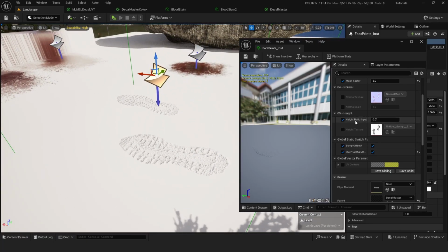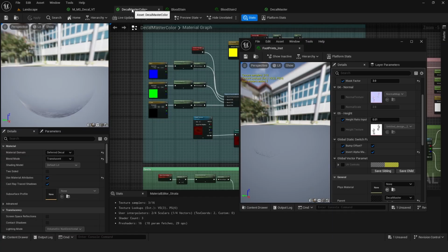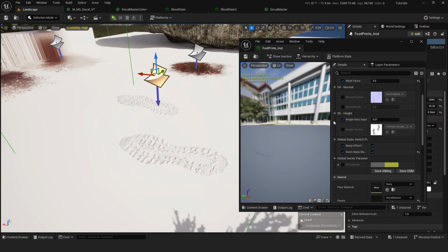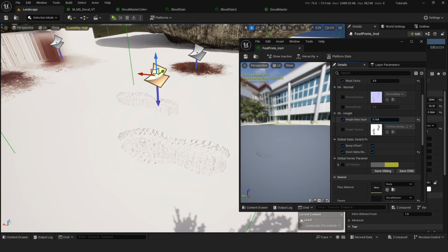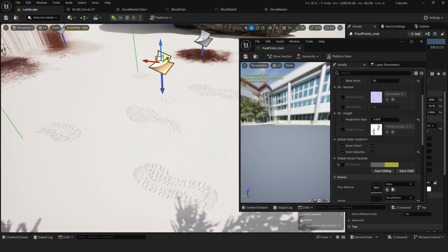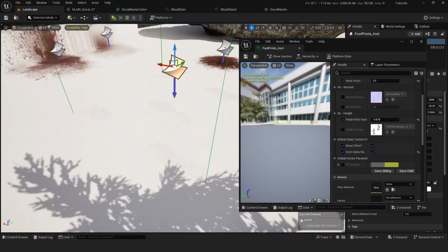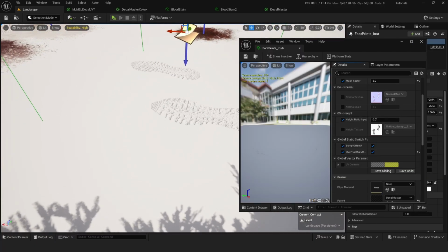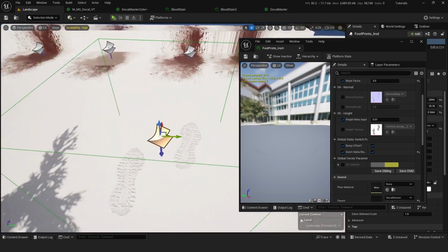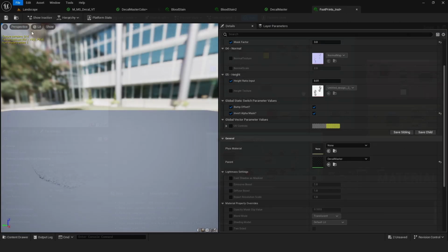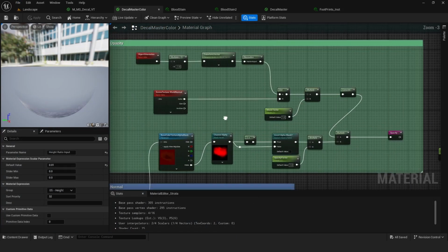And if we change the height ratio input, which was this parameter here, we can see that the 3D effect becomes stronger, or if we go to negative numbers, it's like it's going down into the plane. This is up to you. I found that a value of 0.01 is enough to look okay. Let's leave this back. The next part that we're editing is the opacity.